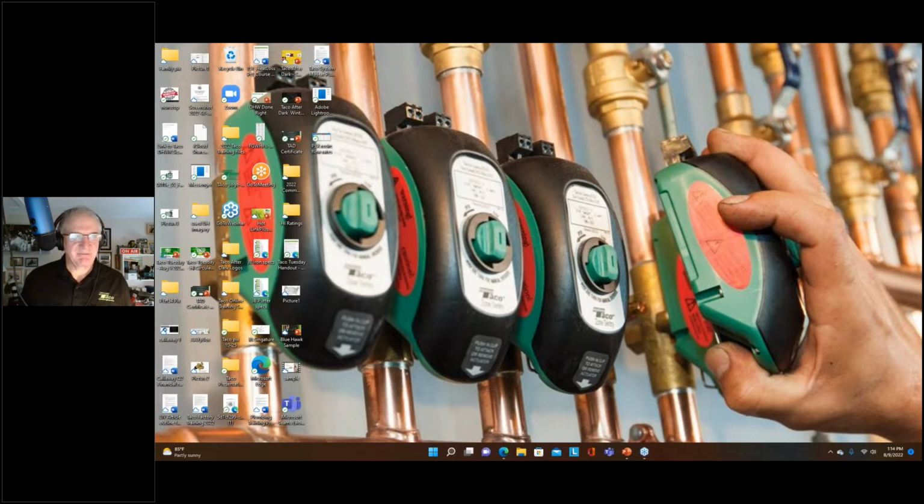And what makes the System M so unique is that we have not only the outdoor unit, which is a real high quality German engineered outdoor unit that is made for us by our partner in Germany called Dimplex, one of the world's leaders in heat pump technology. They're taking care of the outdoor unit. We're building the indoor unit, which we call a hydro box that has virtually everything you need in it. Buffer tank, all the electronics, all the pumps, everything is there in the box except your system pump. You will need a system pump, but there's 2 circulators built in.